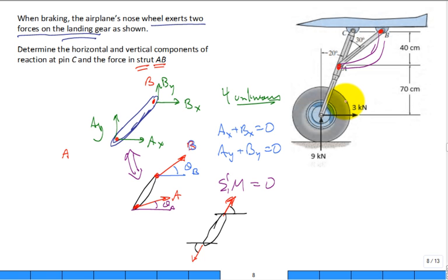Yeah. And guess what? It would still be in either tension or compression along the line of action, or axis, going between A and B. So even the curvature, it doesn't have to be a straight strut. Almost all struts are straight, but hey. Okay? All right. So there's our discussion of a two-force member and how it applies here.